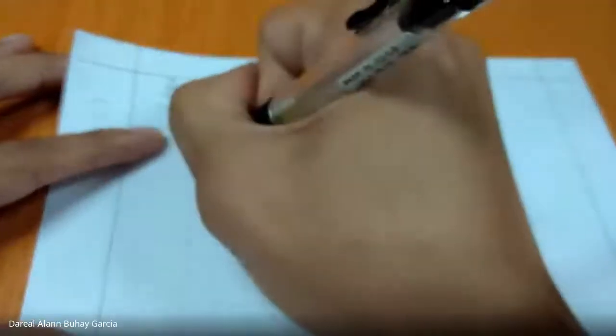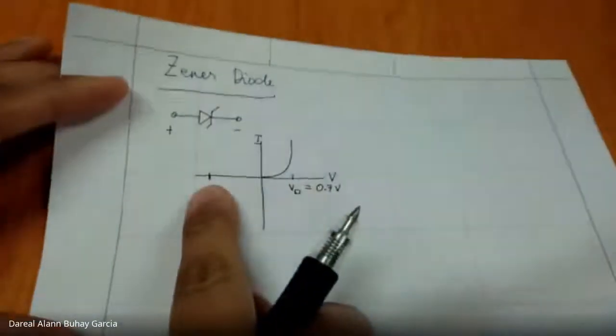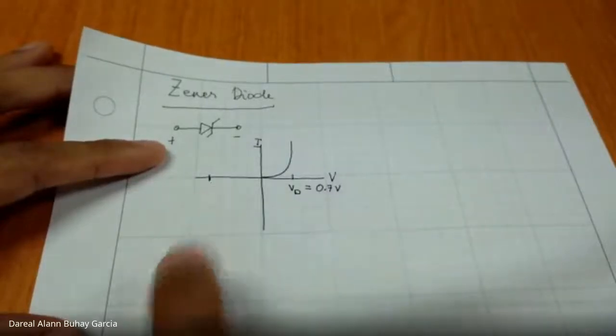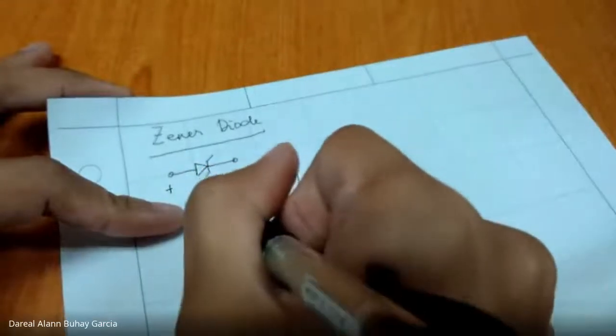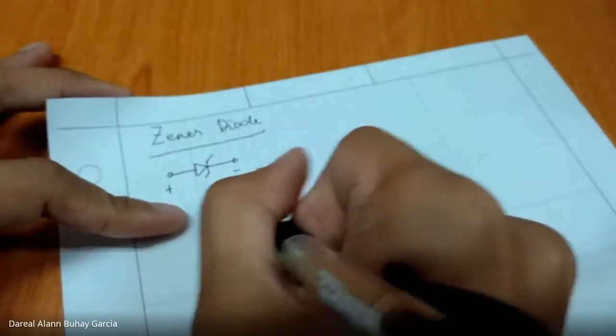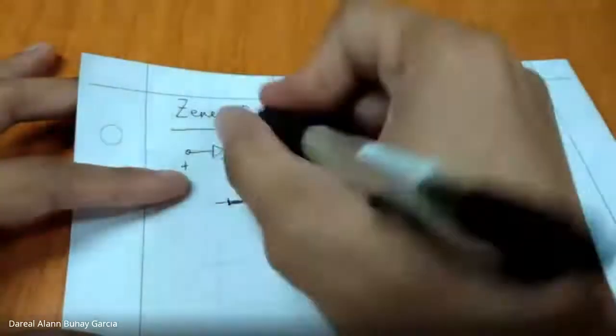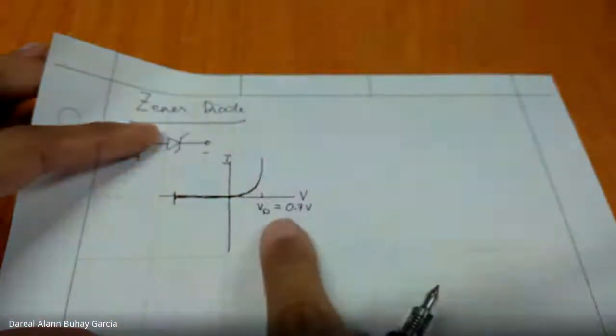Remember, there is a specific negative voltage, relatively higher than 0.7, greater than negative 3 volts in magnitude. Before it is reached, as we have observed in our circuits, when the diode is reverse biased, the current is zero. The diode conducts here, at a positive 0.7 volts.